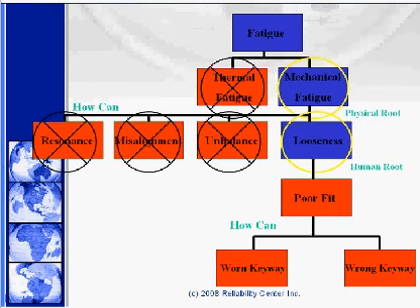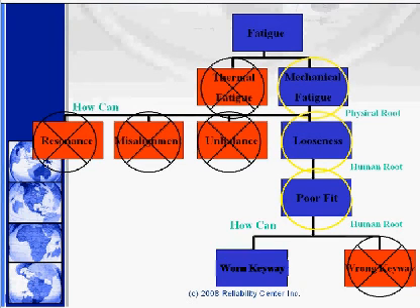As we continue the investigation and collect more data, we'll be able to identify further human and latent roots that can build a story. So in the case of the shaft that you saw earlier, there was a worn keyway, which contributed to a poor fit.